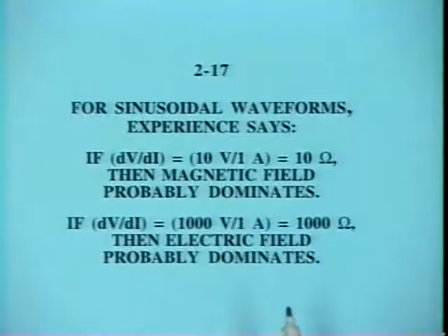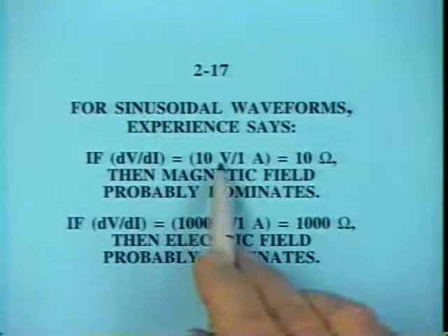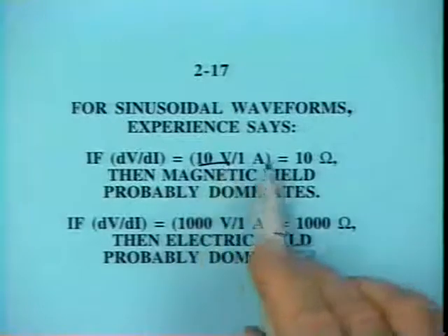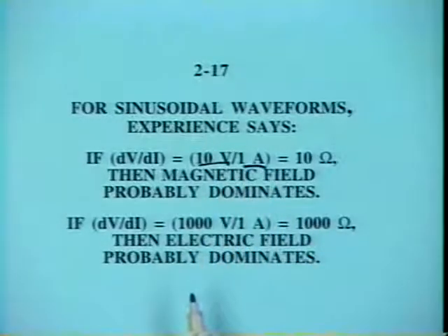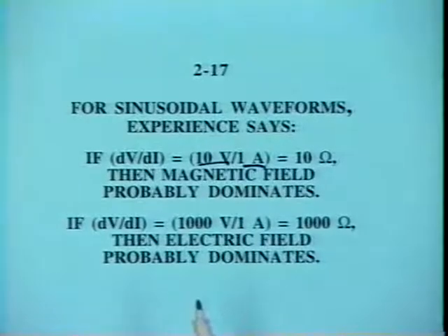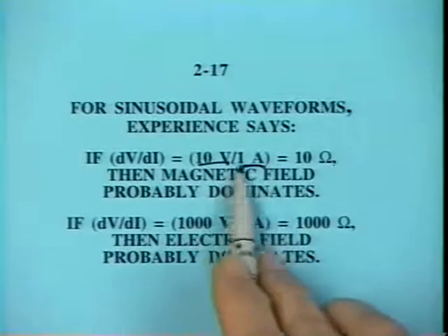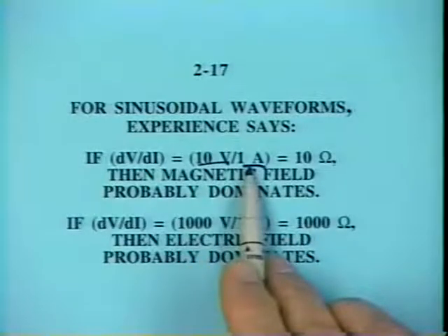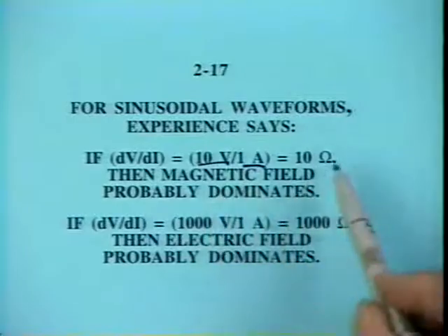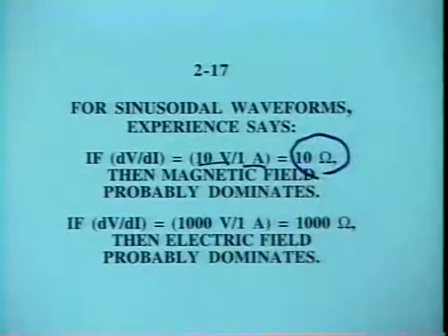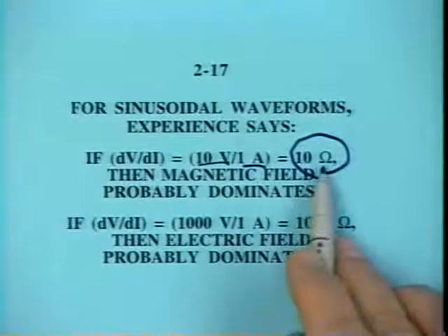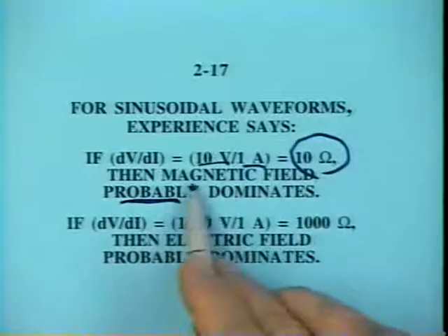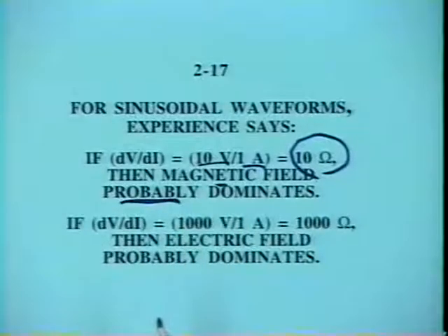Now, let's say this cable that's generating noise troubles, in one case it's got a 10-volt signal on it, and the signal current is 1 amp. Signal is 10 volts and 1 amp. But that signal is causing a noise problem, coupling something through the air. Well, because of the large current relative to the voltage, 1 amp I think is large relative to 10 volts, that goes along with an ohms number of 10 ohms. A low ohms number means generally a lot of current relative to the voltage. This number suggests probably, not for certain, but probably a magnetic field coupling problem.